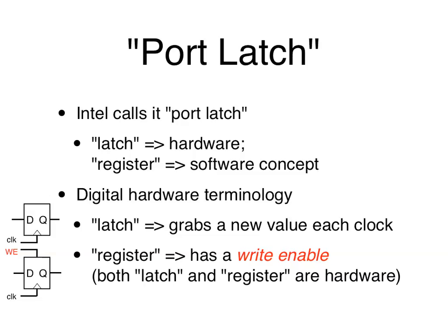Okay, so port latch. This is a term that Intel uses to refer to the D flip-flops that are associated with the port. But I would say this is a rather exceptional use of the term, because I think in Intel terminology, when they say latch, they refer to the hardware concept. When they say a register, they refer to the software concept. Okay, even though they might end up being the same thing. But if you look at everybody else in the world, not Intel, then that's not how they use the term. Even TI, even though TI implements the 8051, they still use different terminology.